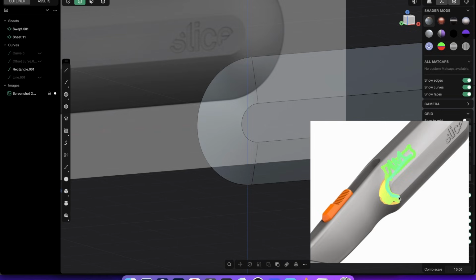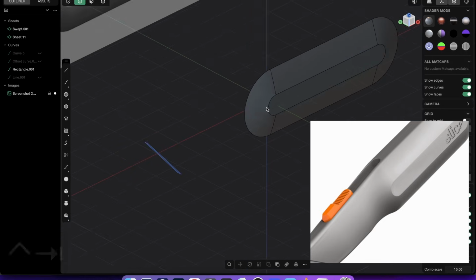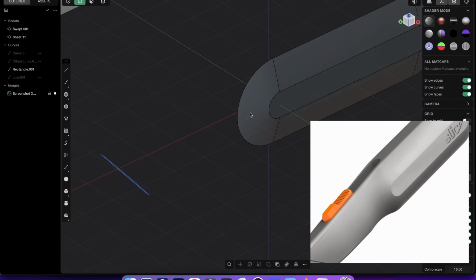So this, okay, so this will be our surface. And here we will leave the hole and then later patch it, because we will need this little piece of a surface. So we have then G1 continuity information. So it's again hard to explain. So I will just show it to you. But what we have to do, it's very simple.